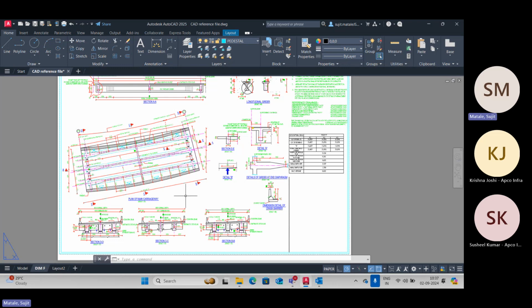Any finite element program will have a basic structure. You will have to define nodes. Between two nodes, you will have to define elements. Let us for now limit our discussion to beam elements. Elements can be of different types: a beam element, a quadrilateral element, a triangular element, and so on, also cuboidal.